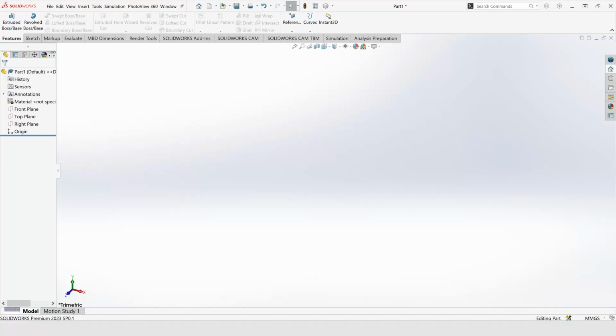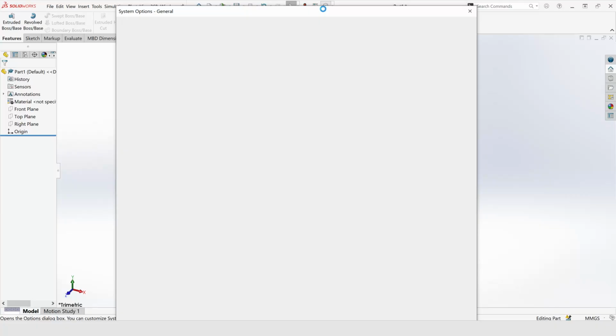All right, so let's get into setting up our drawing so that we can start making our cylinder. So the first thing you want to do when you start a new drawing is set it up. Like set up your units, set up what is the basis for your drawing. So I'm going to go to options, which is this little gear-like thing, and click on that.